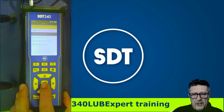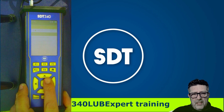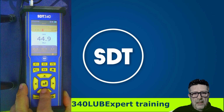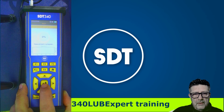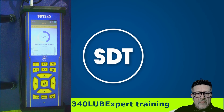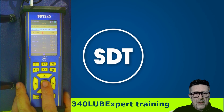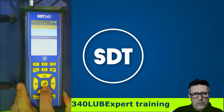I'm not doing lubrication. So I will select my sensor. This is, let's say, my regular condition monitoring task. I will set up the amplification and I will take the measurement. It goes smooth without changing the sensor. If I'm in the same position, I'm not even moving the sensor at all. It stays where it is. I'll press enter, save the measurement, and move on to the next one.